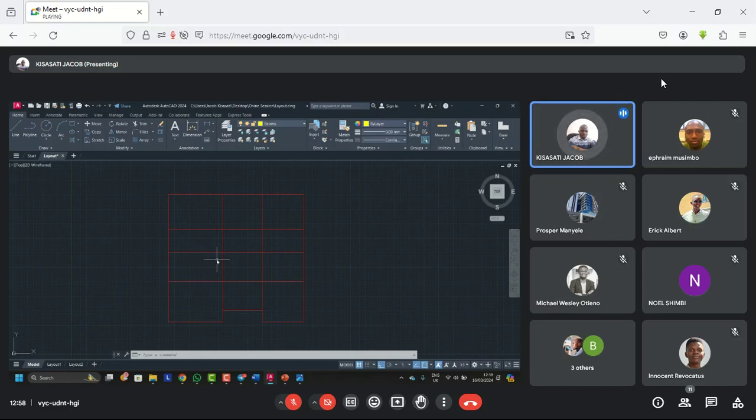The other day I discussed with one of us from Zimbabwe. They have been using, and in Nigeria, they always use 230 by 450. So let's figure out that one. I'm telling you this because if you go with the deflection criteria, you will end up getting something like 200 by 196. Like the depth will be too small. So just go with what is in the field right now.